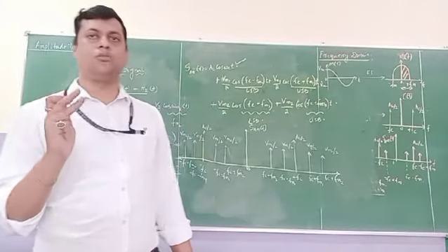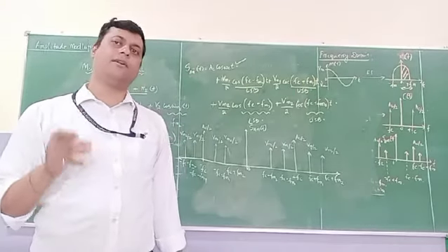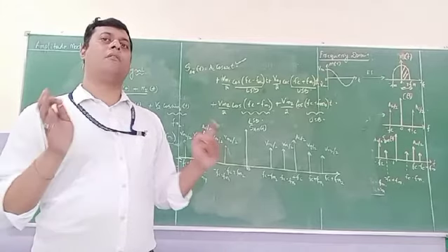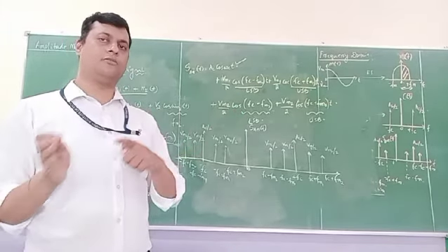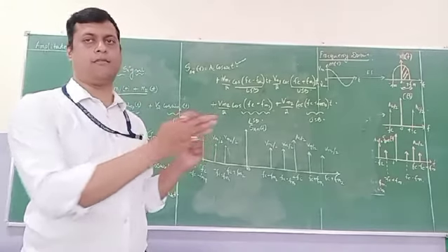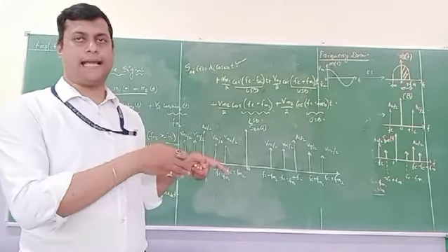Here there are two modulating signals, which means it is a multi-tone signal. We have considered two signals, that is called multi-tone. So two signals means four spectral components will be available, two on each side of our carrier.